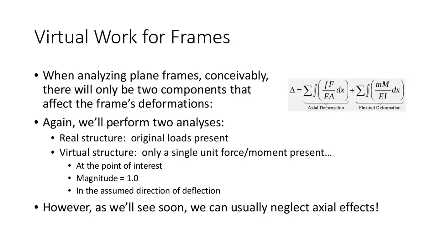Again, we would have a structure with the real loads present, and then we'd have a structure with all the loads removed and only a single force or moment present at the point of interest with a magnitude of 1 in the assumed direction of deflection. And so we would have not just a series of moment terms that we would have to sum up, but we have axial terms as well. Now, if I was trying to be as non-specific to frame behavior as possible, then this would be an expression that we could use.